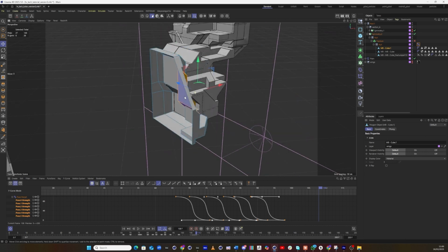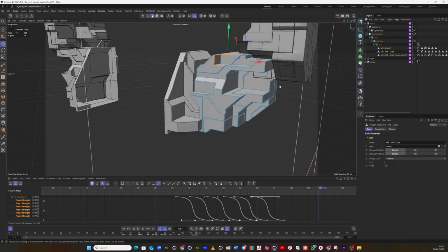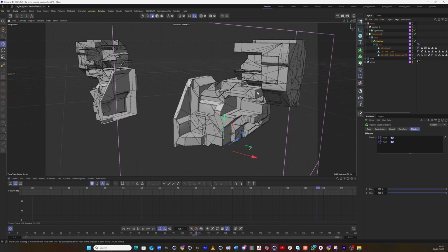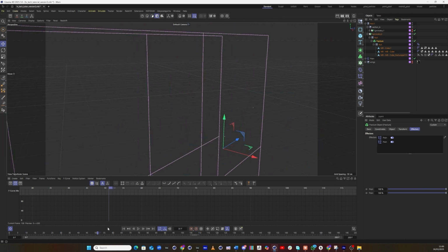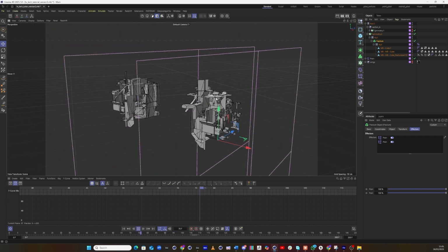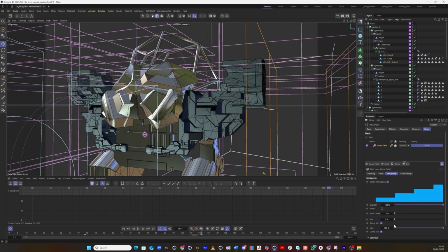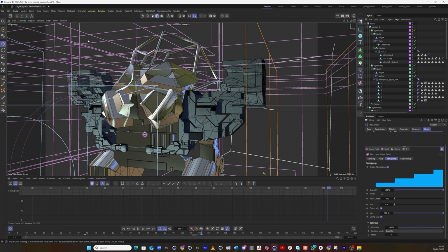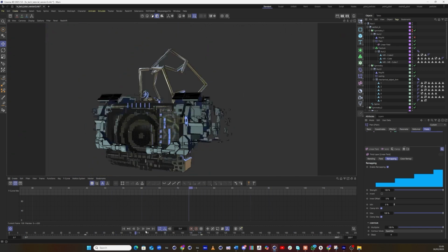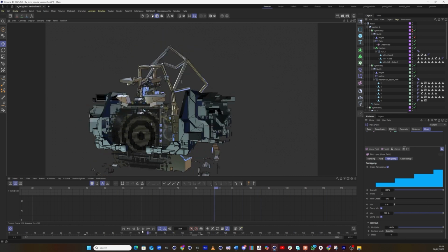Since each piece was created with the Mesh Boolean plugin and separated into different elements, the fracture is set to explode segments mode, allowing us to control each shape individually. It is a combination of these techniques that creates the mechanical robotic effect. One important detail to remember: when using the effectors with a value of -1, I also applied quantize in the field remapping. This helped achieve the precise mechanical feel we're looking for.